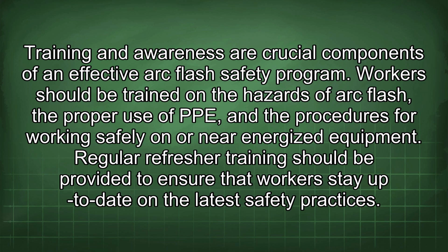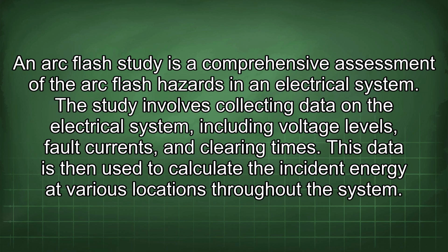An arc flash study is a comprehensive assessment of the arc flash hazards in an electrical system. This study involves collecting data on the electrical system, including voltage levels, fault currents, and clearing times. This data is then used to calculate the incident energy at various locations throughout the system.